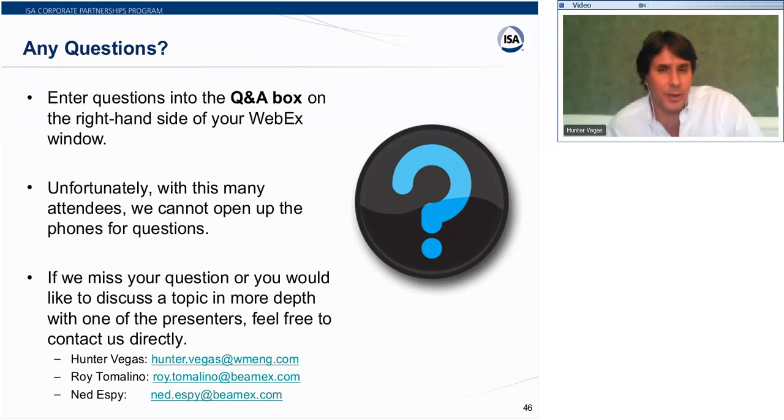Robert, I guess to answer your question, that's probably one that you're going to take up with your vendors, and just send him a picture and show him what you've got, and then see if he's got a particular connection that'll match up with yours. The flush rings work very easily on a flange connection, but if you have a screw connection of that kind, then it may not. So you may end up creating your own flush ring or some other, maybe you put in a couple of T's and taps or some way to easily drain that section of line.